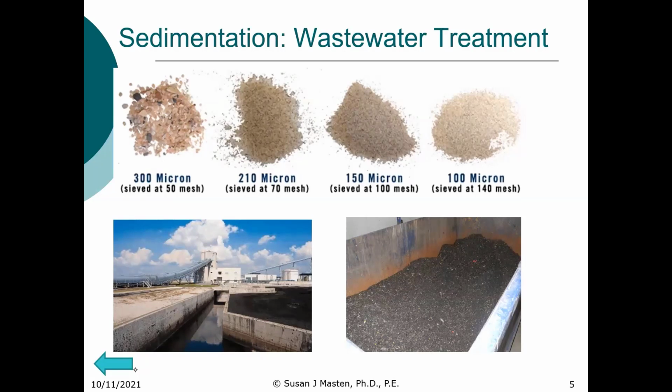It's mostly inorganic material that we're removing. We're trying to keep the organic material in suspension. We want essentially inorganic, non-biodegradable material to settle in this grit chamber.